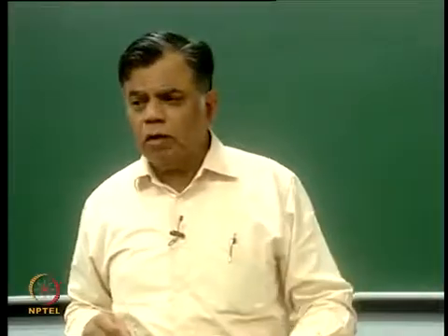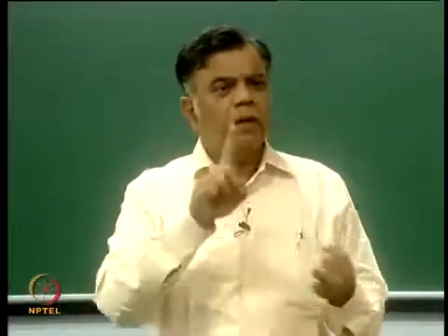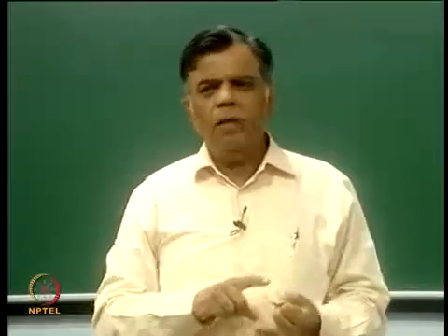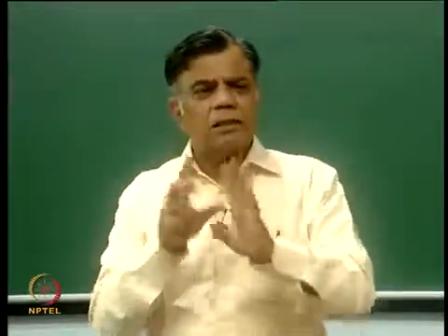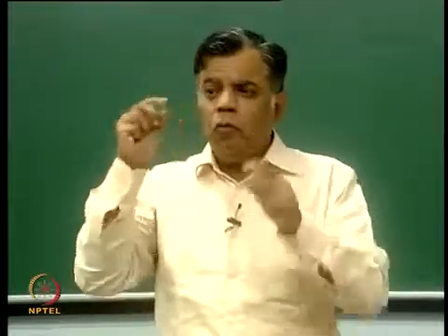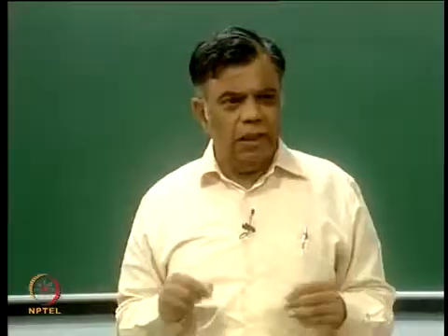H is a function of what then? Give me the variables. That is a flow condition, geometry and the properties. Therefore, it is not a property, it is a characteristic. Now I am coming to this point, Q is equal to H delta T or HA delta T, we should not be strictly calling it a law.